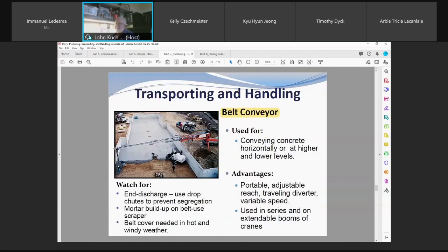Here you have a concrete pump, okay. A lot of homes now, even residential, are going to pumps, because with the narrower lots, at one time a ready mix truck could get into the back or between a house and a new house being constructed, and he could actually pour the basement walls going around. Now they can't. So you'll see on most residential constructions, they're using a pump. Okay, they'll park the truck on the front street, the ready mix producer will come up and he'll boom over and pump it into place.